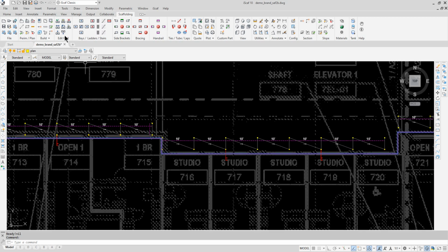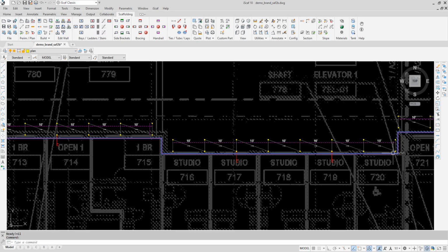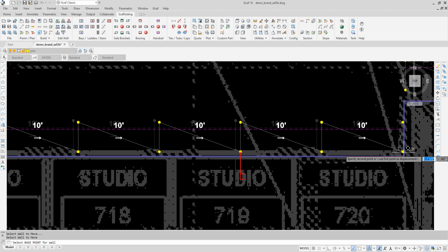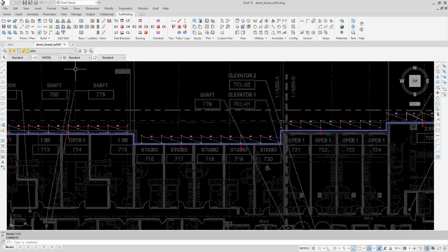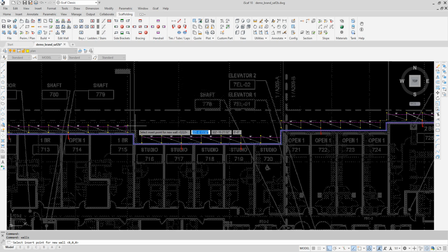So we can move this wall over, so we go to the Wall Move option again, then from this point, move it right into the corner. We need to make it a bit closer than that, so let's press the space bar to try again so we can make it right up close to the edge. And then we make another single bay wall from this point to this point. It's going to be a 10-foot bay, and we can move that into position as well.